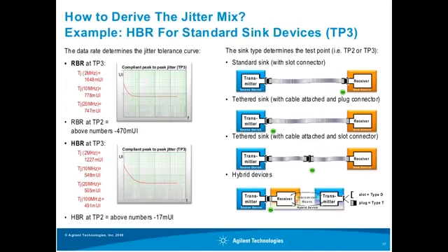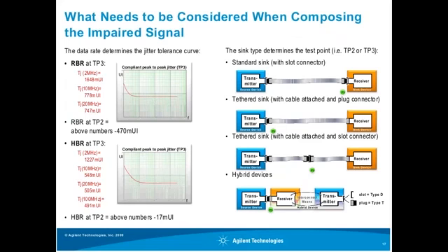You saw that curve before for high bit rate at test point 3. There's another curve for reduced bit rate, which looks slightly different. And I have noted the total jitter numbers from that curve for certain frequencies. And if we change the test point, actually we have different ISI numbers which account into here, and therefore those numbers here need to be subtracted by 470, and the same is true for high bit rate with minus 17 at TP2. So what about these test points, TP2 and TP3?